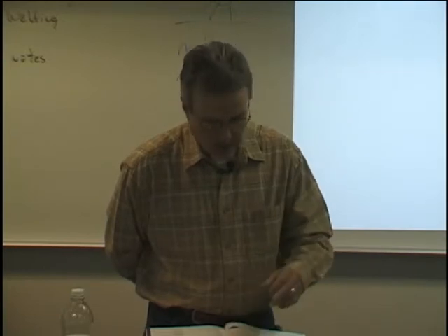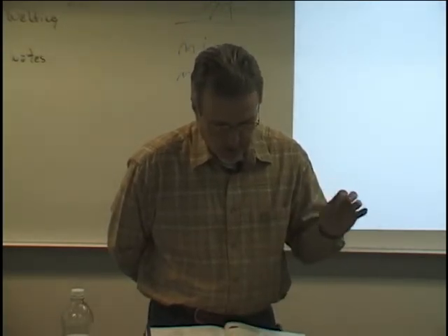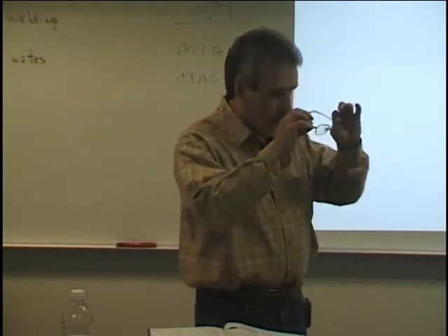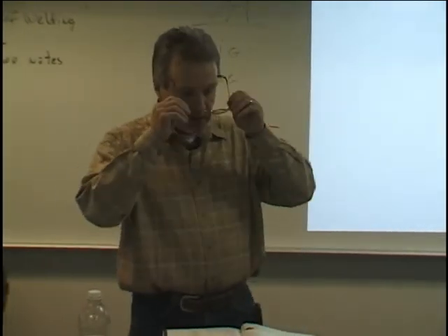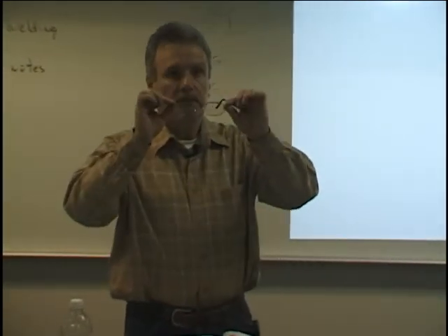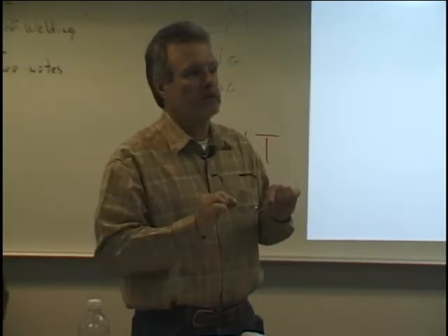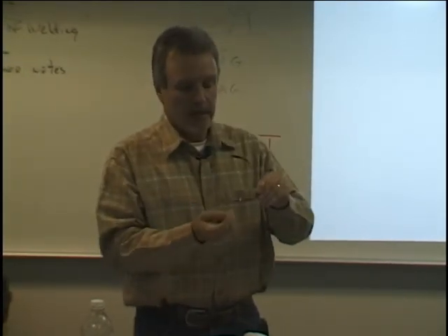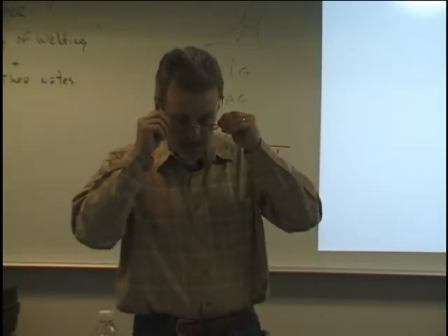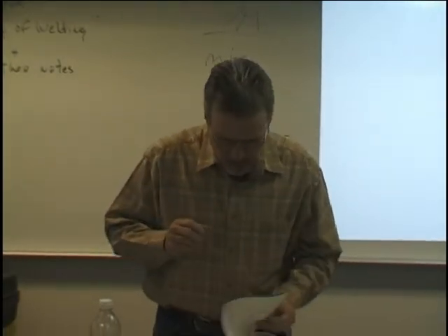And then one last thing I want you to put in your book, write it off to the side someplace. Even clear safety glasses will knock out 75% of the harmful ultraviolet rays from reaching your eyes. Clear safety glasses, which is one reason we insist you wear your glasses at all times in the welding lab. Even these will stop 75% of UV rays from reaching your eyes. Okay, that covers the book.